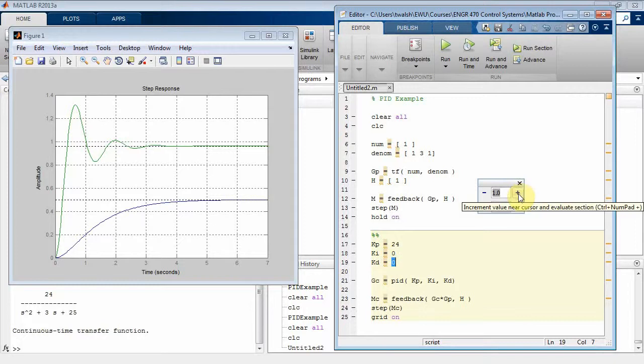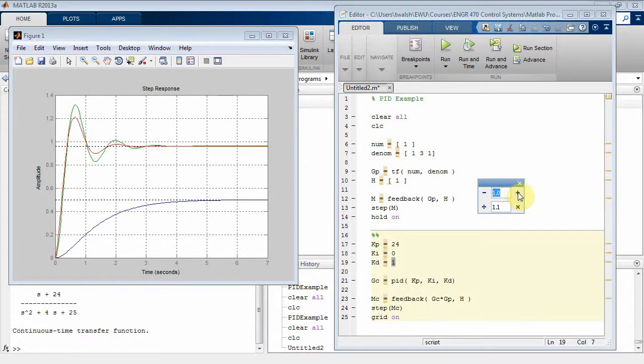Now look what happens to the response. Hey, we're starting to damp out our oscillation. Now, don't say damp. Damp is the wrong word. We're starting to add bandwidth to our system, which allows higher harmonics to come in, which allows me to get edges in our signals. Discontinuity and edges are really high frequencies. So we're allowing more high frequencies to come in, and look at the response. Yeah, we're actually going up there and boom, making a hard right turn and kind of stabilizing, as opposed to that ringing effect, which means you're filtering out the really high harmonics.